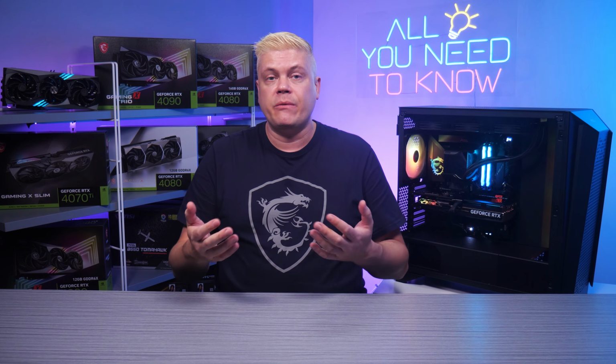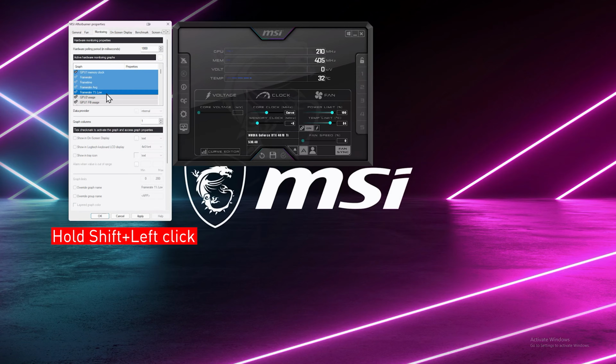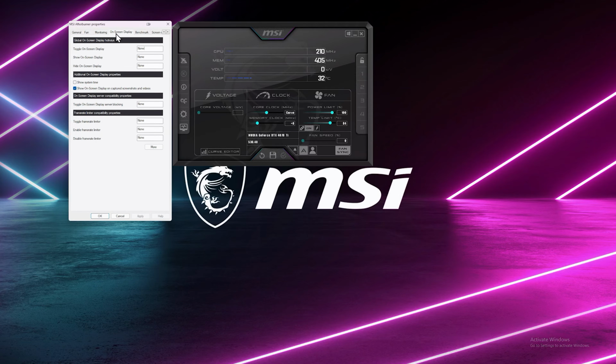Now that we have everything we want together, click on the top item and mouse wheel or drag the sidebar down. Holding Shift, click the bottom item to select them all. We'll click on the check mark on the left side to enable monitoring these stats. Then we'll click the box to show in on-screen display so they show in the OSD, and click Apply to save your changes. At the top, we'll click on the On-Screen Display tab.